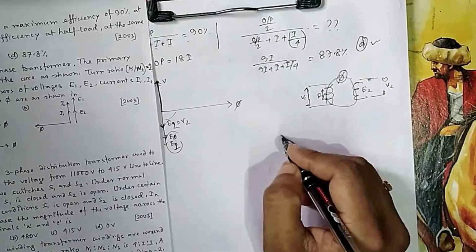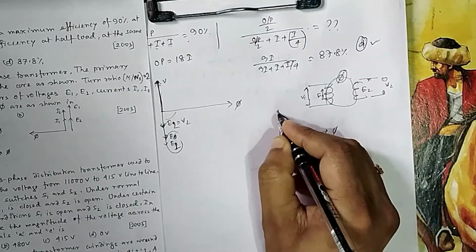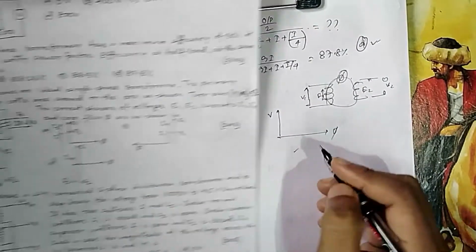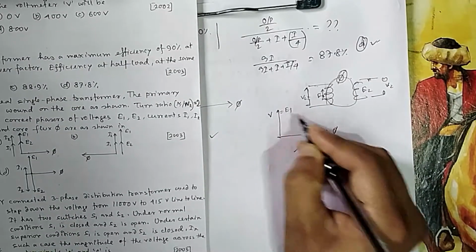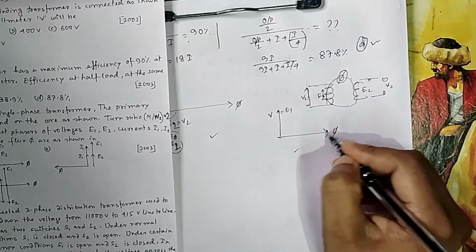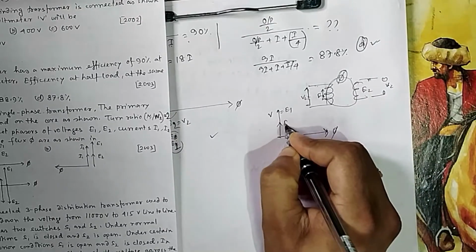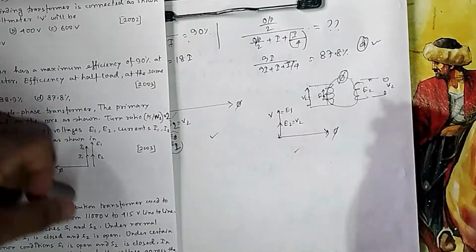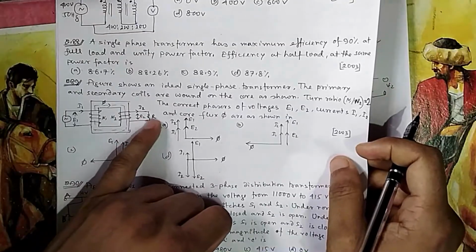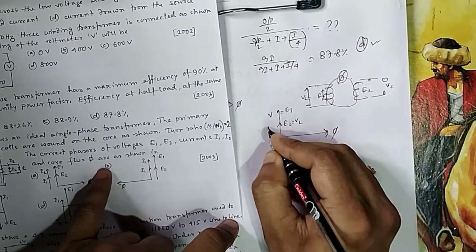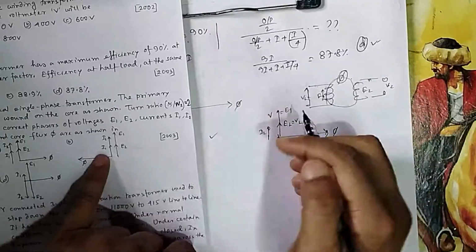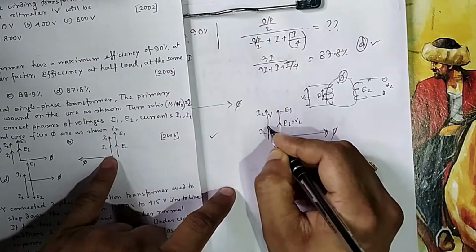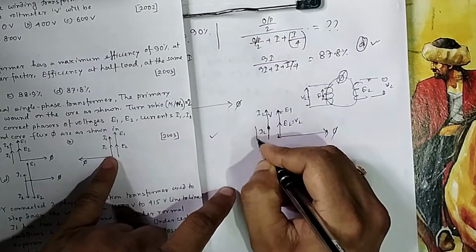One can think of it in this way also, because both are correct. These are the two ways this phasor diagram can be represented. If you do KVL here, V is equal to E1, since no loss is there. Once it becomes E1, which is generated due to phi, E2 is also generated due to phi, so E2 will be in this phase too. Here the load is resistive, so V2 and I2 will be in the same line. I2 will be more because the current ratio is the reverse ratio, and because E1 is there, I1 will also be in phase.